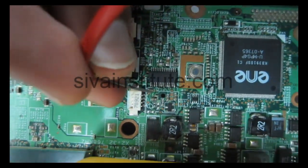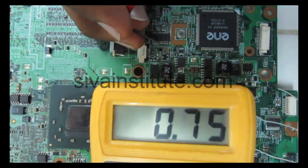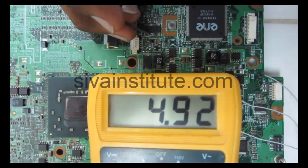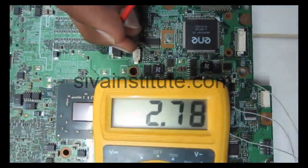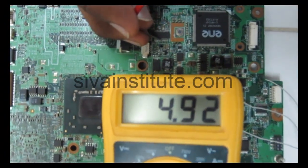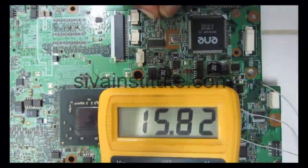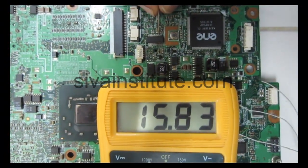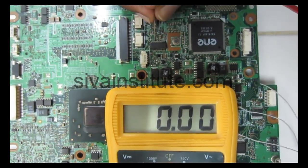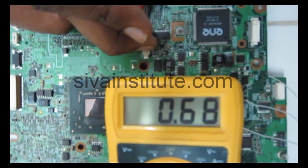We will see here without the S4 command, pin number 21, 4.95 volts, okay. Pin number 22, 4.9 volts. This voltage is also okay. Pin number 4, 15 volts adapter voltage. Pin number 11, 0 volts. Pin number 26, 0 volts.